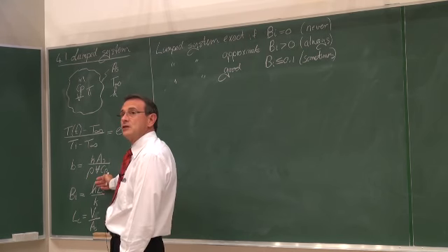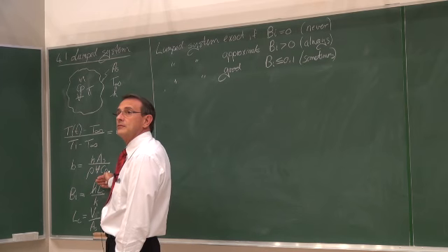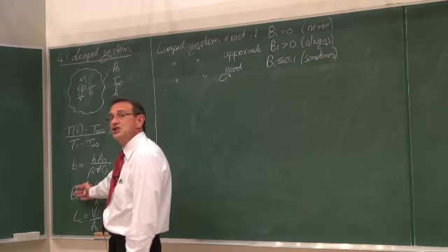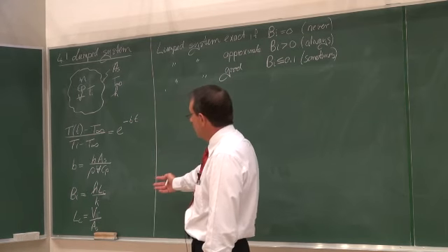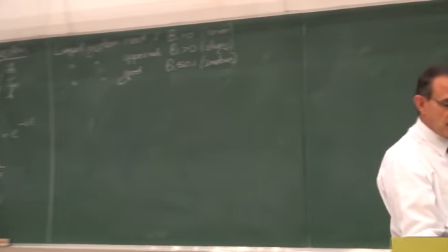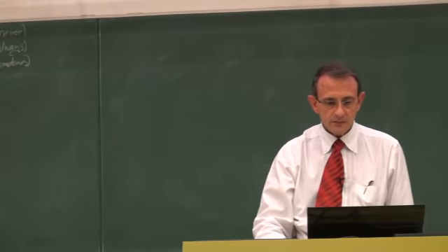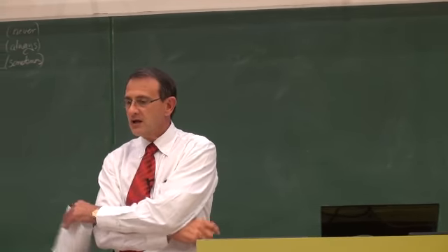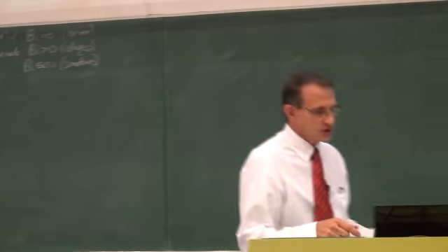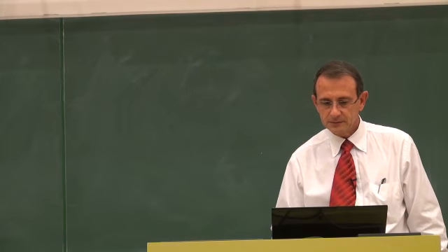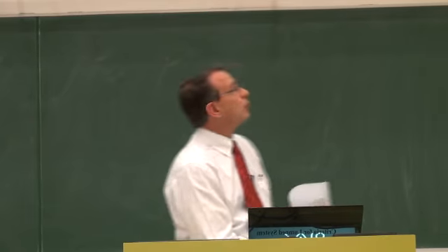And then the question was, when can we use the lumped system approach? The lumped system approach can be used by using the Biot number. The Biot number is the resistance ratio inside the body divided by the convection resistance at the surface of the body. So if you look at that sketch that I've drawn yesterday, this one is a little bit more neat.